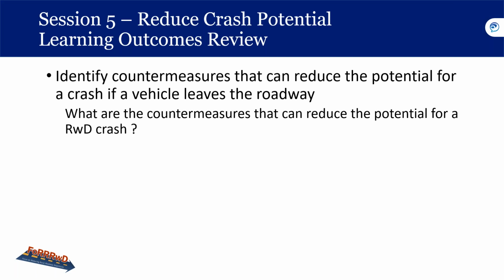David just typed in, is there a program in Ohio to remove trees near roads? I see a lot of removal along Route 78 east of Nelsonville. Well, I would say the program begins with contacting that district's safety engineer, somebody on the district safety review team, and you can begin those discussions with them, and they can bring up some crash data, and maybe they already have a file started on particular trees.